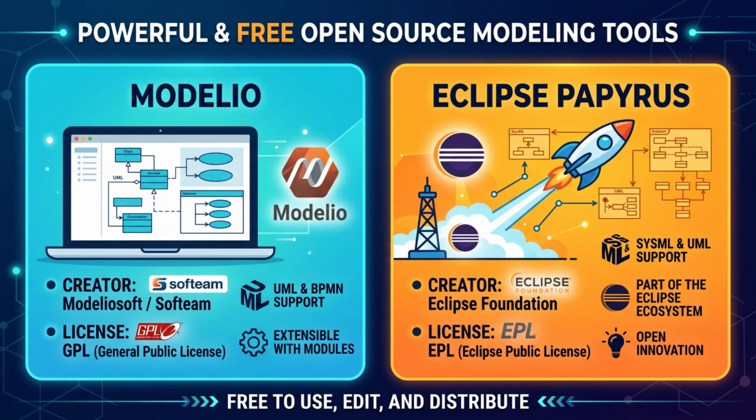Of course, whether you're looking at the expensive commercial options or the free ones, there are a ton of different factors you'll need to weigh when picking the perfect software. But if I can give you one massive piece of advice, it is this. Whatever you choose, strongly consider making sure the tool is XMI compliant. Now, XMI stands for XML Metadata Interchange, but all you really need to know is that it is a special standard that lets different modeling tools actually talk to each other and swap data.